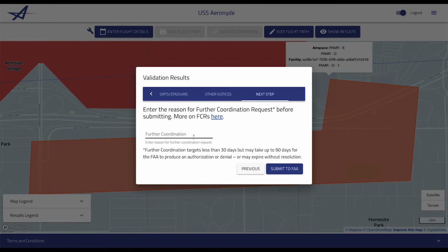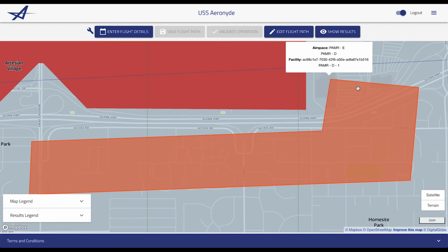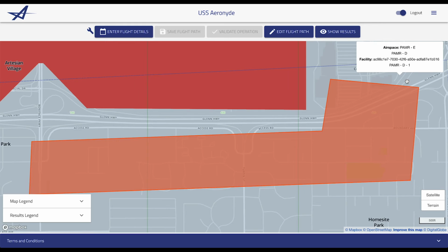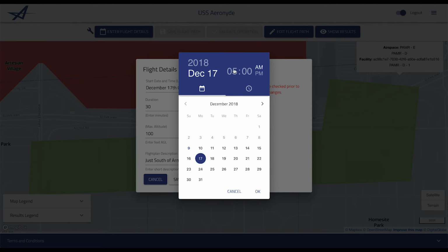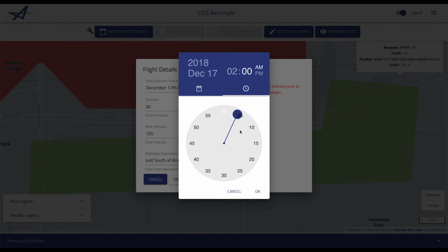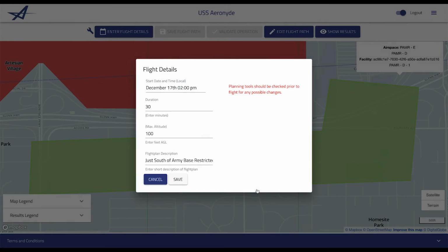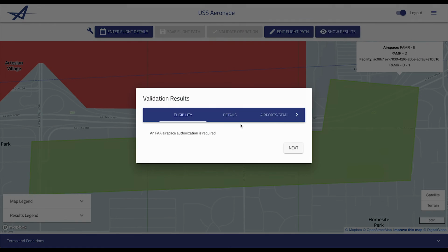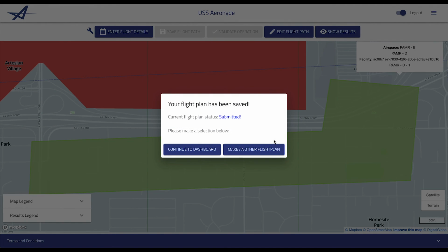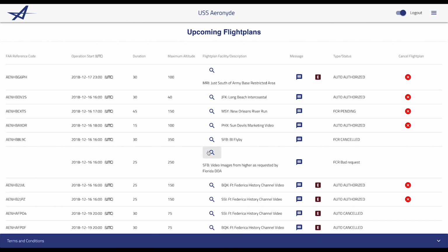The benefit of this is that we avoid waiting on a manual review by the FAA. This all assumes that we do not need the extra 50 feet to successfully complete our flight operation. The operation was also during night hours, so we need to change that to daylight hours. Now that we have successfully changed it to daylight operating hours with an acceptable altitude, it is available to be submitted to the FAA for auto approval.